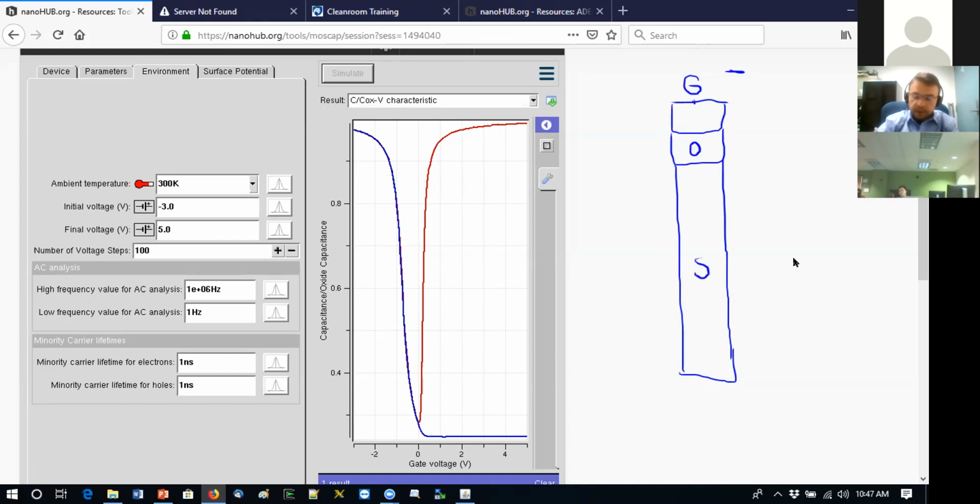That's our semiconductor. It's p-type, so it's rich with holes. So once we apply the negative voltage, all of the holes would try to go there, attracted under the force. And what will happen? Well, it's already a p side, and this portion would be even richer. So we would have a p plus kind of region here.